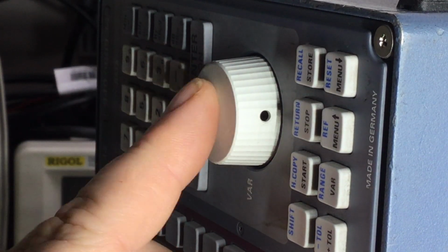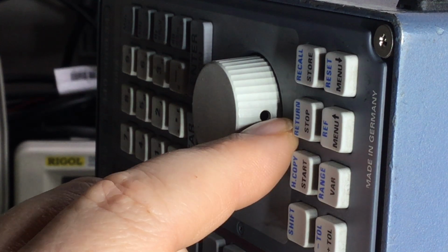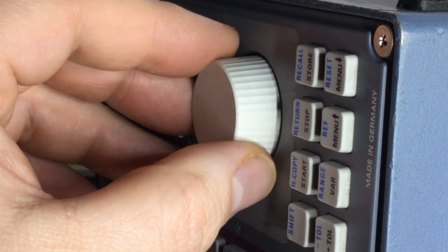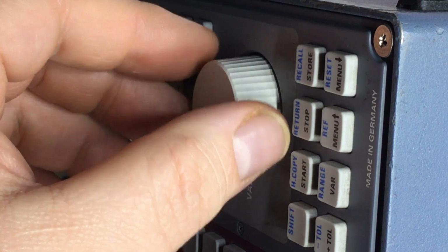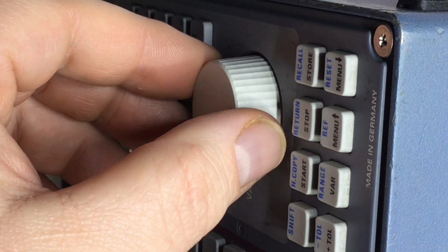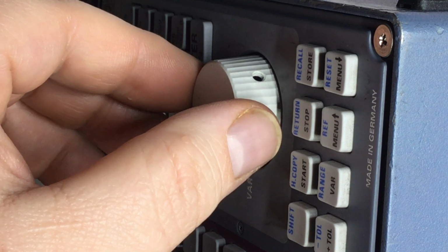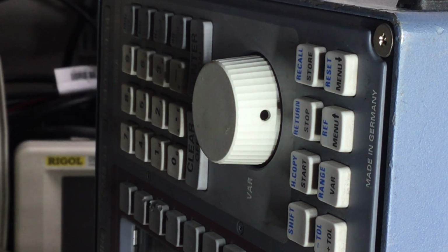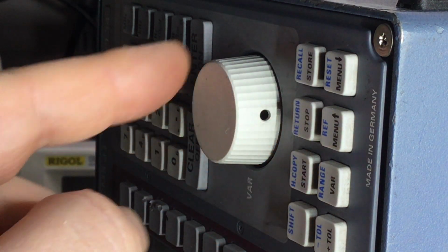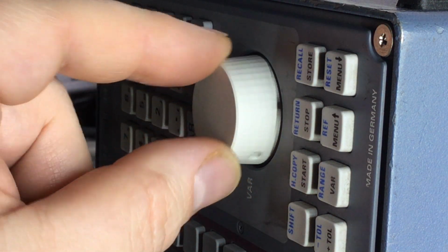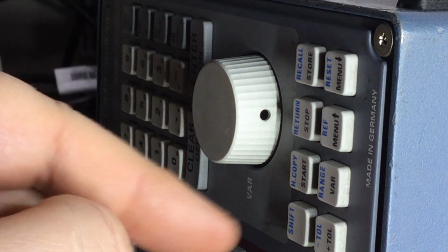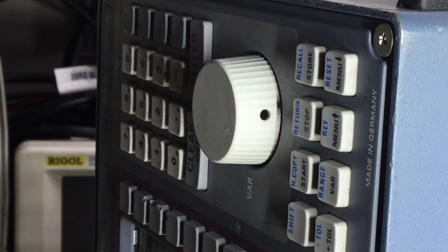Right, so just count how many detents there are in this rotary control, starting with this reference point in line with this key. So it's 1, 2, 3, 4, 5, 6, 7, 8, 9, 10, 11, 12, 13, 14, 15, 16, 17, 18, 19, 20, 21, 22, 23, 24. So there must be 12 north and 12 south. Otherwise it would obviously be 6 north and 6 south if we did just 12 detents all the way around, but because there's clearly 24 detents going all the way around, must mean there are 12 north and 12 south poles on that magnet.